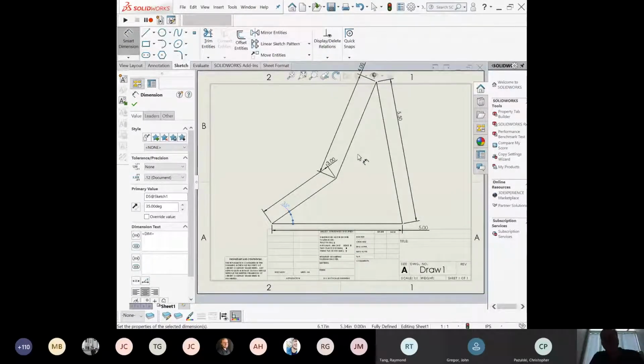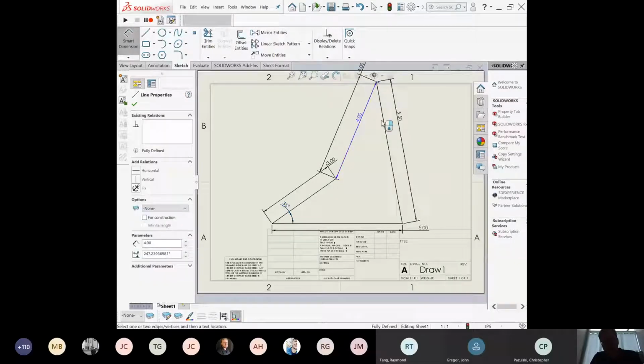Now, I talked about, so there are various angles in this thing. When you did a version of this problem for the prerequisites, you found all these interior angles. We'll talk more about those angles, but this top one right here has a particular name. That's the transmission angle. It's a measure of how efficiently force is transmitted from the coupler link to the output.